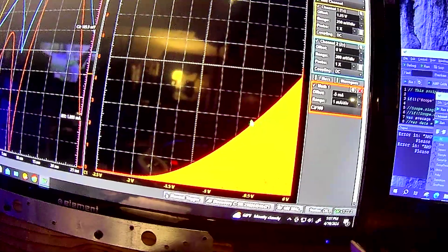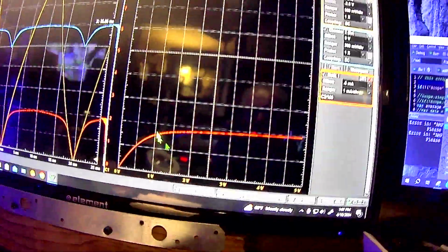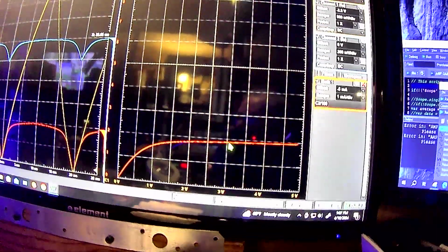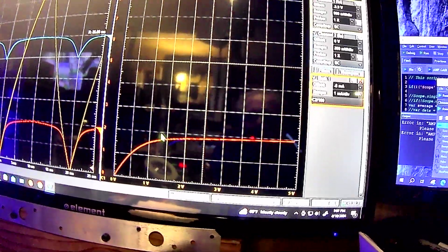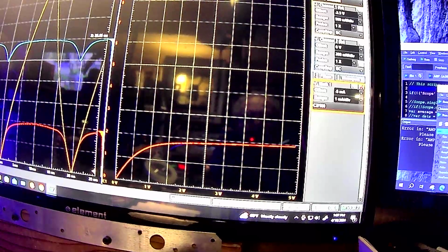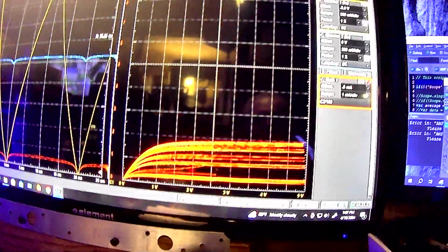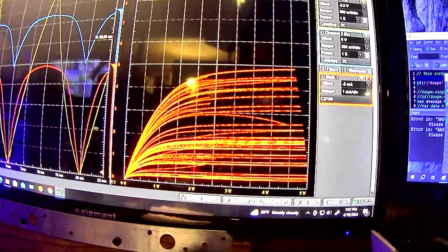This is the transconductance curve, so it's not visible, and that's why a family of curves is still really handy when working with any transistor, because you can tell where the ohmic regions are, and by sweeping across it, you can see where you want to bias it.